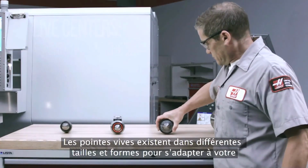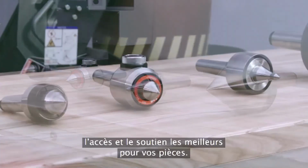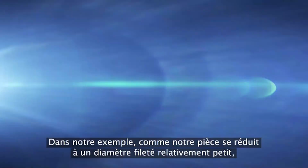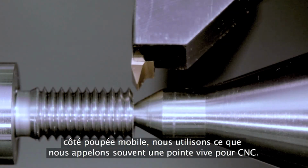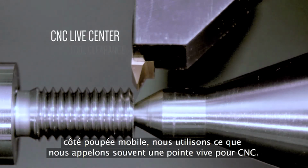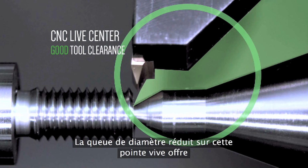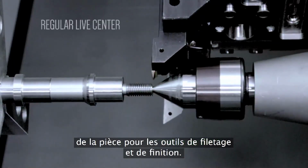Live centers come in many sizes and shapes to fit your tailstock while allowing the best access and support for your parts. In our example, because our part reduces to a relatively small threaded diameter at the tailstock side, we're using what's often called a CNC live center. The reduced diameter shank on this live center allows more room near the end of the part for threading and other finishing tools.